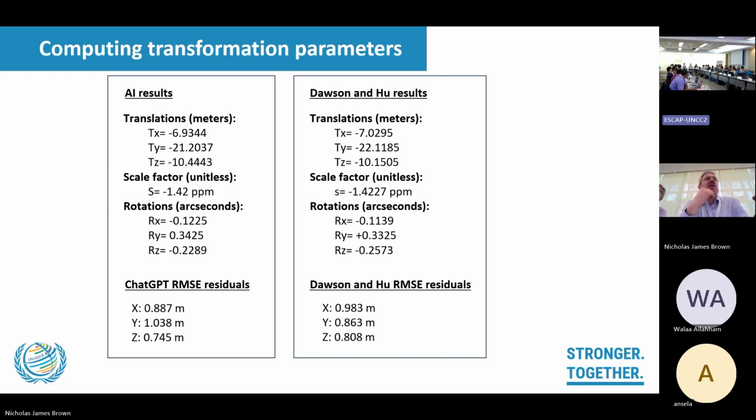That's good to know. I think that's helpful for some countries, because as you said, that is broadly the assumption. It might have been different in Africa though, because I think they were using the War Office datum, and I'm not sure if that spheroid was designed to have a minimum N value over their particular country. It might have been a spheroid adopted from the UK or somewhere in Europe, which means I don't think you can assume the N values are close to zero, but I can see with the PNG case that you could. What an interesting exercise to run through, to see if it still resolves.